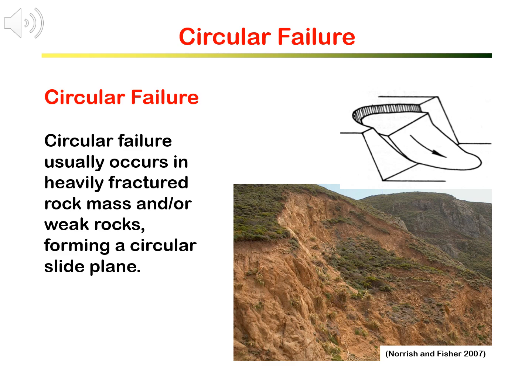It usually occurs in very highly fractured or very weak rocks with no identifiable structural patterns. When rocks are very highly fractured or very weak, they behave like soils. Slopes of those poor and weak rocks also fail like soils.